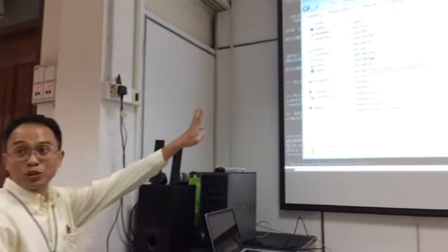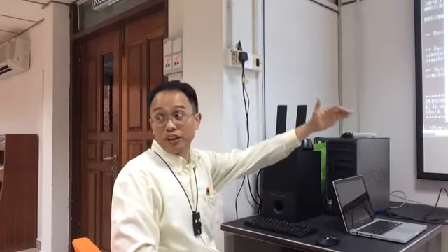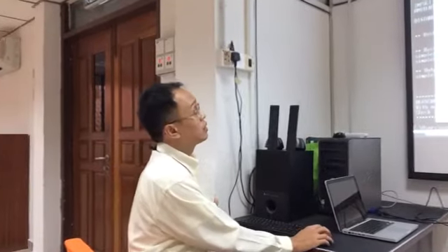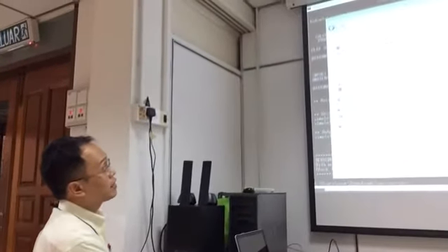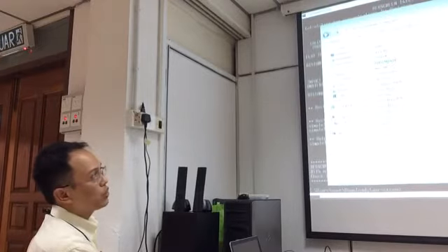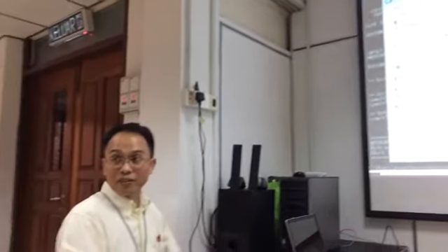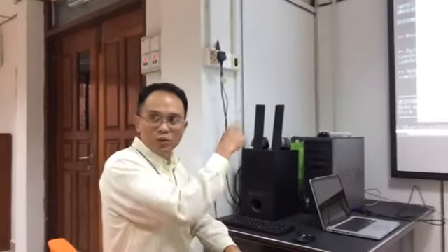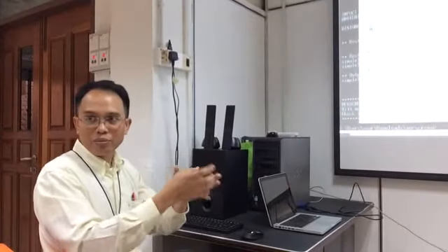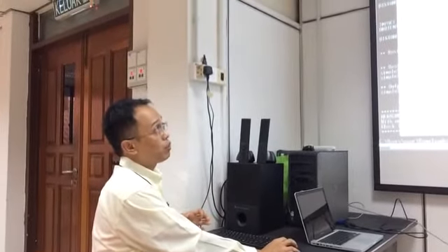Just now there were only 3 executable files, right? These are all the auto-generated output files. This is the executable. And then these are the output files. Most of it you don't need to use. Notice just now this .inp file said it was not found. But then we input the values manually, so it auto-generated the input file for us. This is the AERSCREEN input, the simple one-point input.